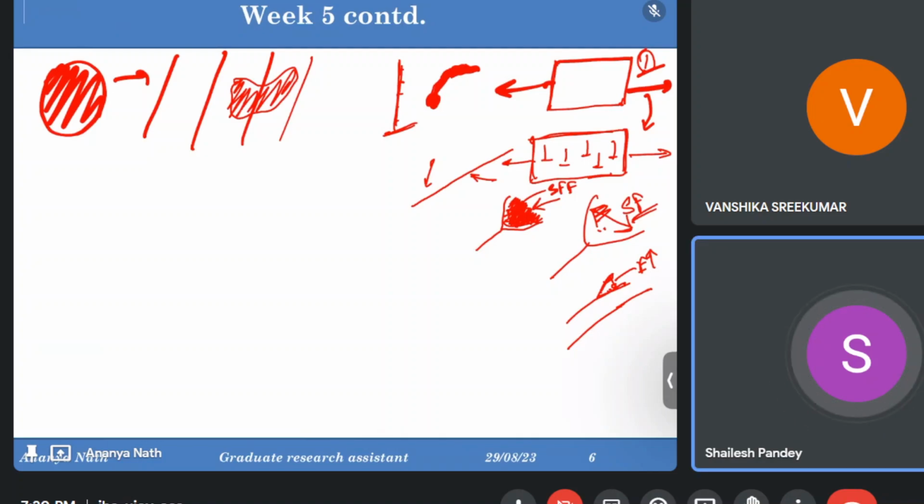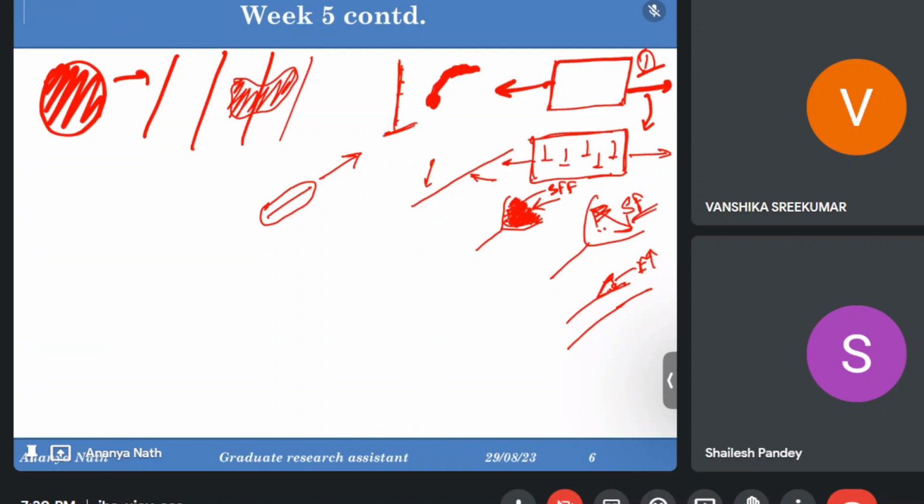So, when we generally use this word dislocation core size, I'm not able to understand whether it means the length of the dislocation is more or the density of the dislocation is more. It means the size of the piled up dislocations; if they are piled up and moving in this direction, this will be the core size. In which direction it's moving, that much dimension. Okay, maximum possible.